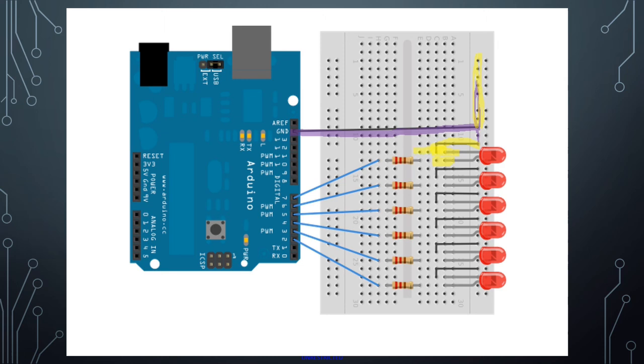So this first connection is made to the ground in its own row, and then in the next row we're connecting to a resistor. Now you might notice, let me get rid of this highlighting, you might notice this resistor is spanning a gap and then it's connecting to a wire in the same row as the LED. So typically connecting multiple things in the same row is a no-no, right?